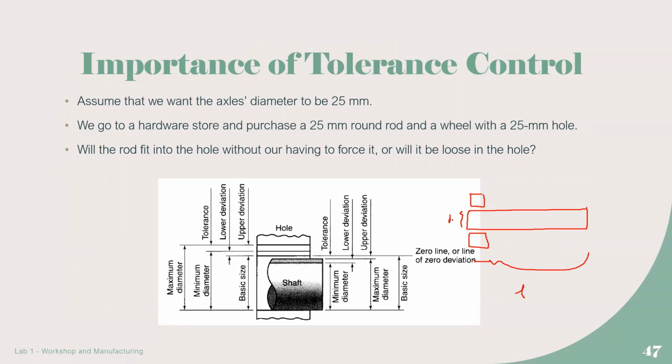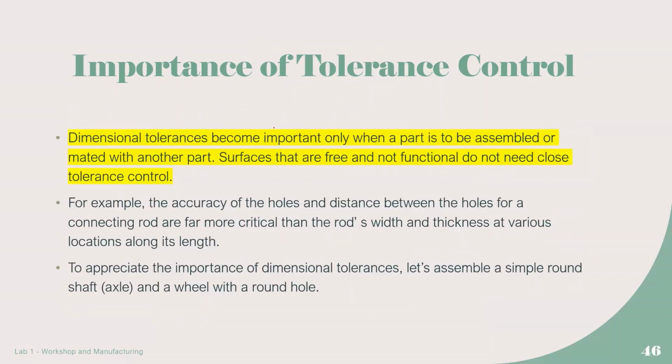Okay. Let's say if your diameter is bigger than what it should be, then it is not going to turn. If it is really less than what it should be, then it is going to make some distortion. It's going to make some vibrations. You don't want that too. So length is not as important as diameter here, as we said before.